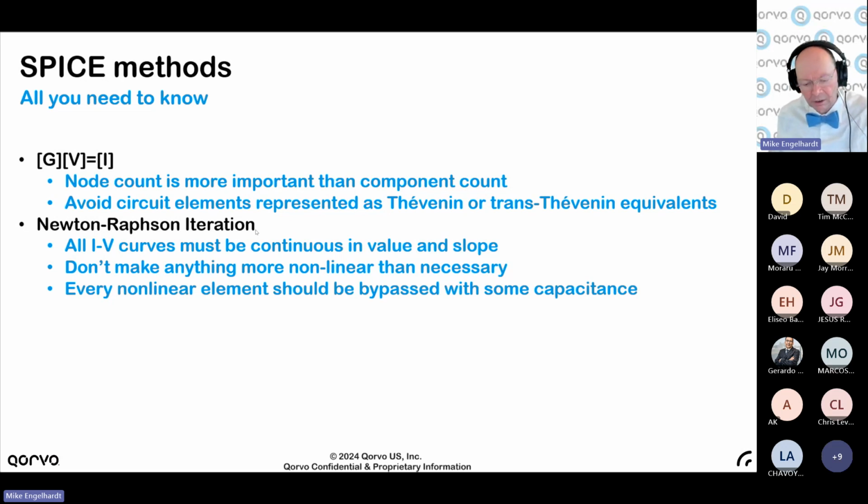It says, look, you've got this nonlinear system. I've got no idea what the answer is to your circuit. But I can approximate your circuit as a Taylor series. It'll be a multi-dimensional Taylor series in each dimension, each voltage in the circuit. It's not exactly your circuit, but it is an approximation. Now I'll solve the system with an approximation to your circuit.